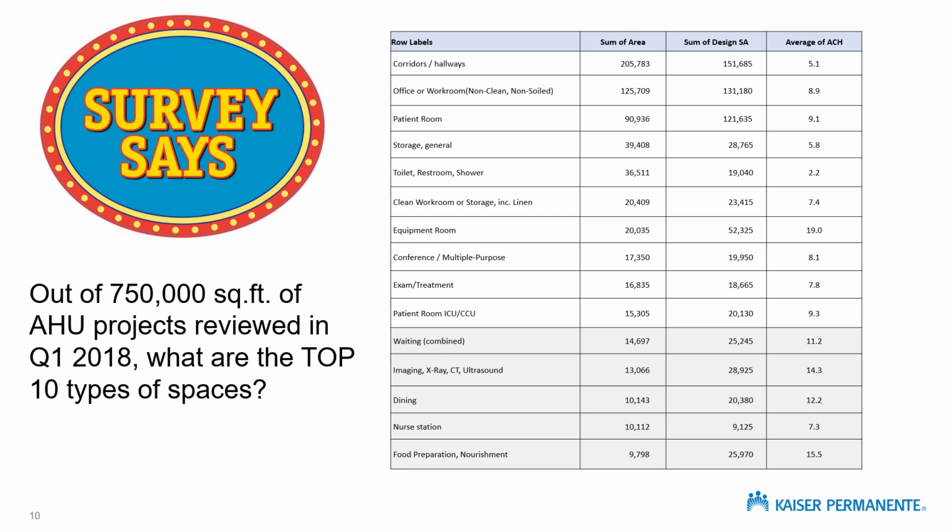So that kind of gives you the feeling here when I talk about that we need to have air systems that turn down in a neutral condition. We have a peak supply air of maybe 1.2 CFM per square foot across the system. And in order for energy conservation, we want to get that 3 a.m. neutral condition down to 0.3 or 0.4 or 0.5 CFM per square foot. There's plenty of opportunity to do that between the peaks that we're designing in these spaces and the turn down condition that we can have in these spaces.